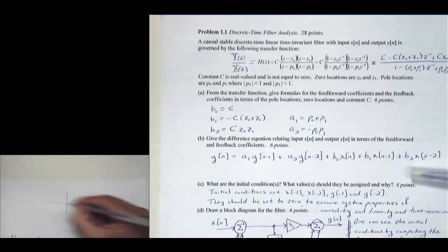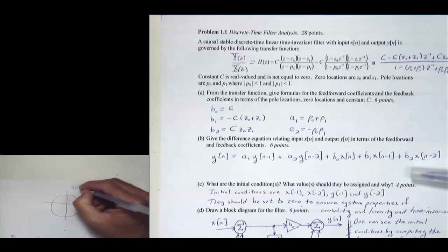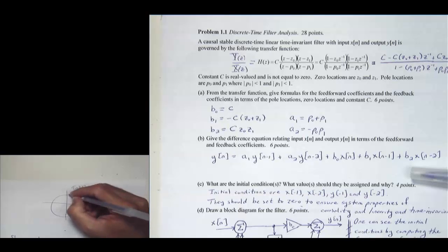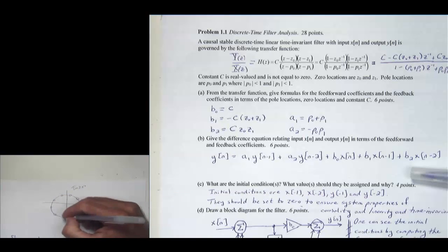Students noted that for an averaging filter in general, I have these uniformly spaced zeros around the unit circle, but I'm missing the zero at z equals 1, angle of 0. And they noted that this angle was 4 pi over n, and that means the bandwidth was 2 pi over n.